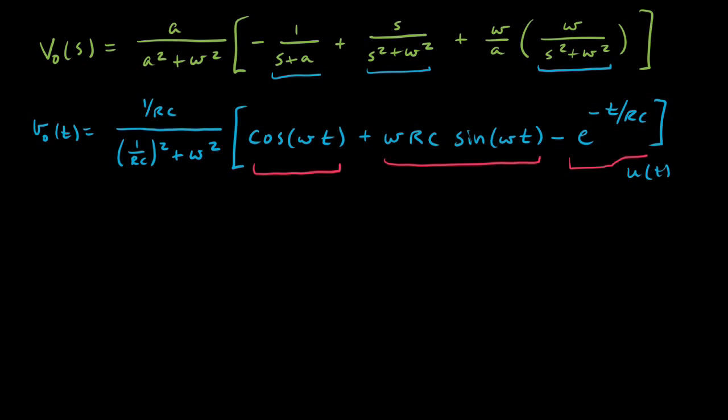We did it by taking everything into the frequency domain using the Laplace transform. Then we rearranged and did some algebraic work to put things in a convenient form, and then we used the inverse Laplace transform to give us back the time domain signal. So hopefully you can see from this that the Laplace transform really is a powerful analysis tool. And we get more than just the sinusoidal steady state response here. We get everything that's associated with the response of this linear time invariant circuit, we'll call it.